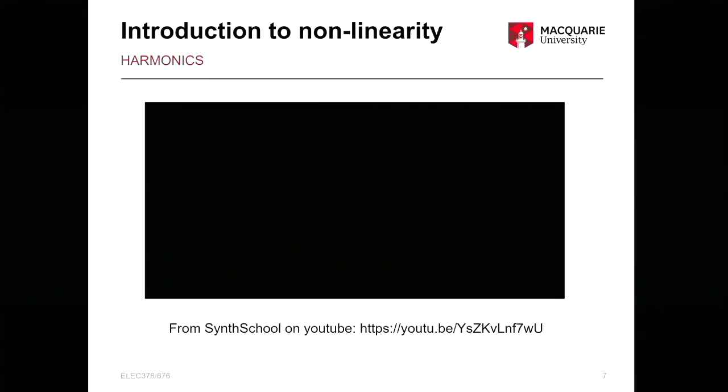So it shows you that a square wave is a combination of many sine waves inside, and they're all the odd components, the odd frequencies. So if you have a 2 kilohertz square wave, that means the square wave has 2 kilohertz and the odd multiples of 2.